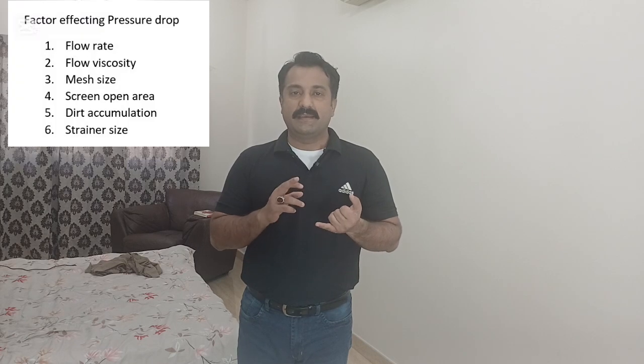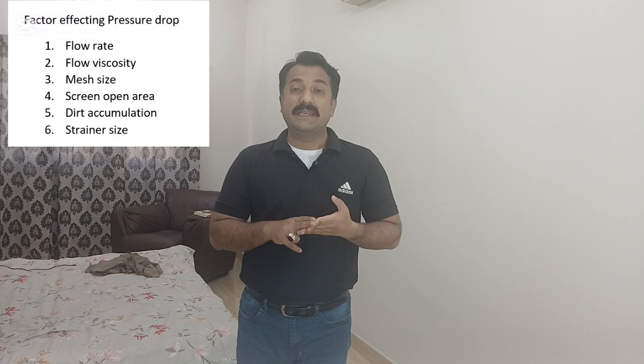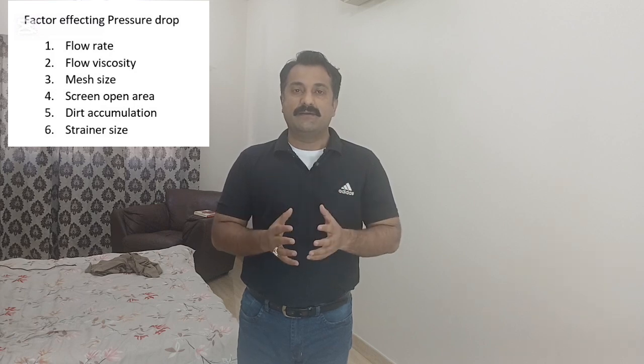There are a lot of factors that affect the pressure drop, like fluid flow rate, viscosity of the fluid, mesh size, open area in percentage, dirt accumulation inside the strainer, and size of the strainer itself.